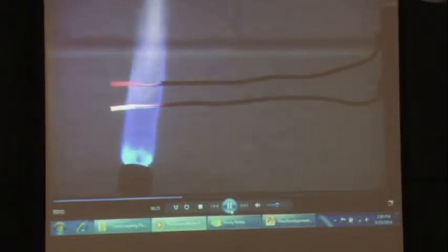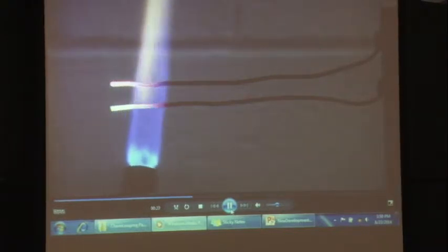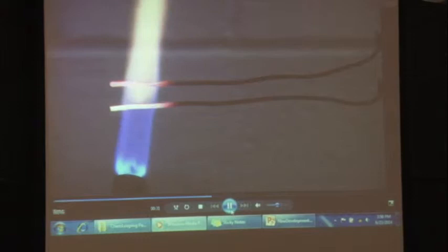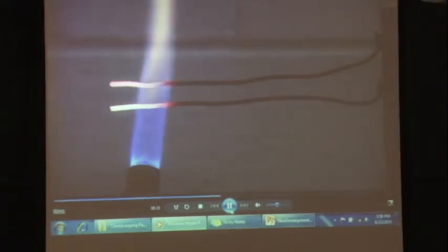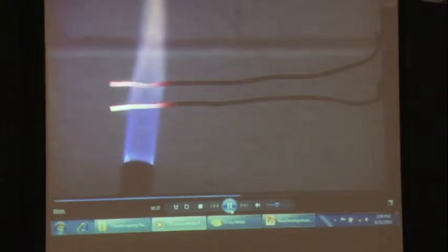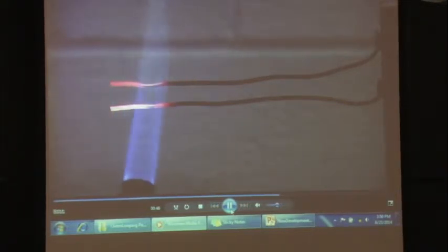So watch what happens right as I move back and forth. Can you see the copper going back and forth to copper oxide? You can see the shiny part there, and as soon as I get that out into the air, it gets dark again. You don't see that reflection because it's going to copper oxide. At least that's what I'm pretty sure is happening there, right? It all makes sense because you can look it up on an Ellingham diagram, and it has to happen that way.